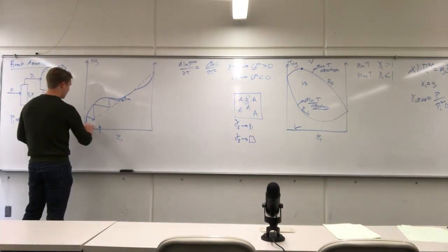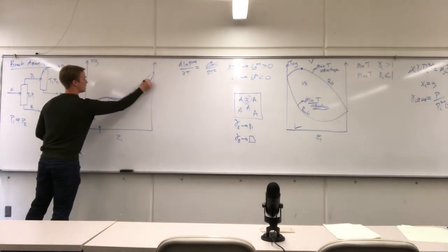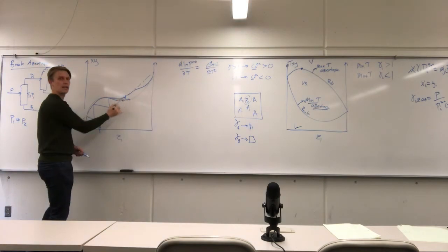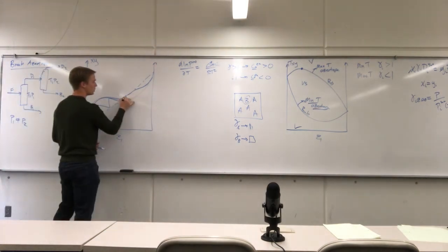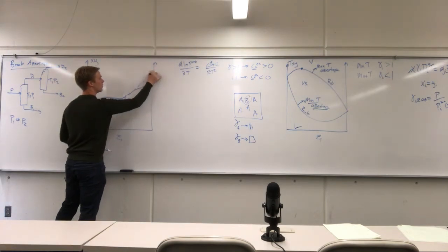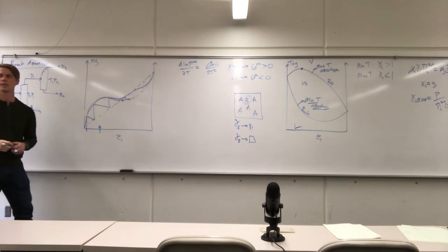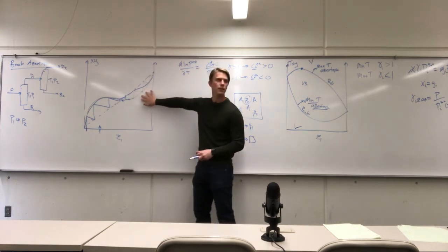So the objective then is you want to shift your azeotrope so that it is now on the other side of your XY diagram. And then you can continue your separation, 1, 2, 3, 4, 5 stages on the other side. Note that the procedure that we've used here on the opposite side of the XY diagram is exactly the same.